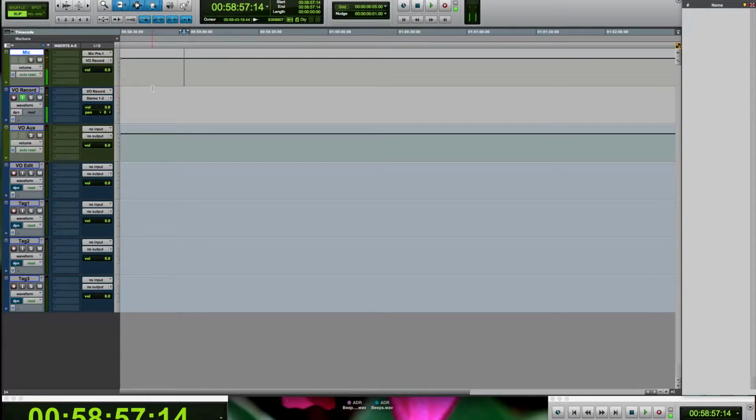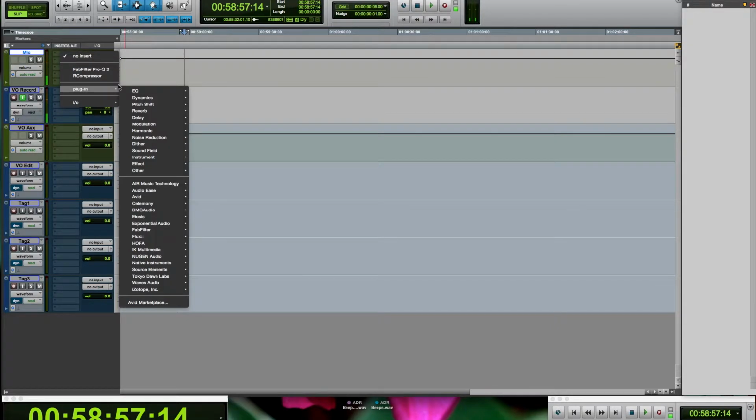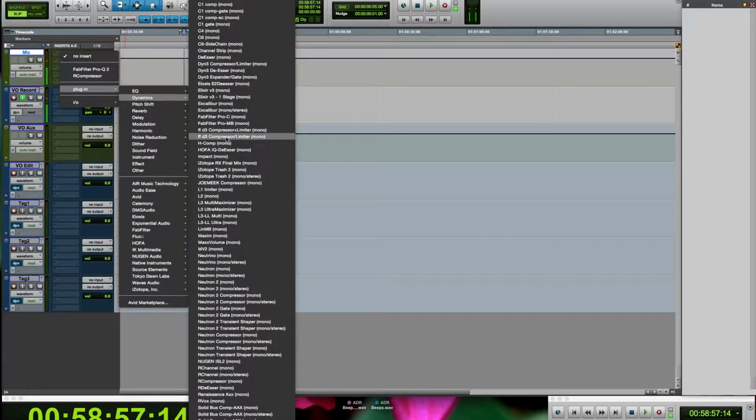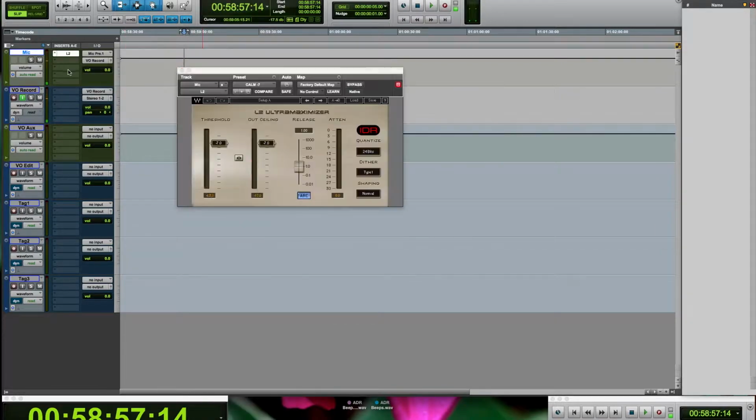So why, you may ask, did I not just put the mic pre input here? Well, here's the reason. You might need to put a limiter on here so that you don't overload your channel. So I'm going to set that pretty high, -3, and that's fine.